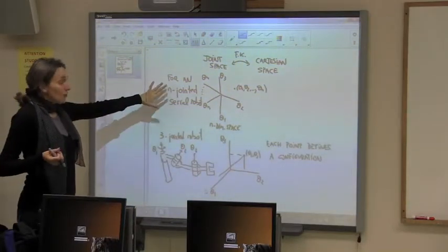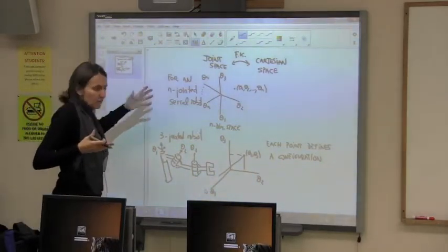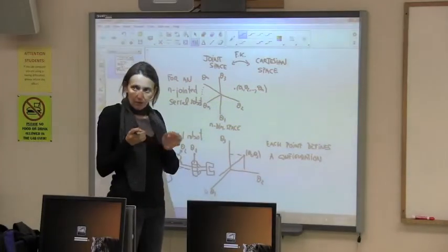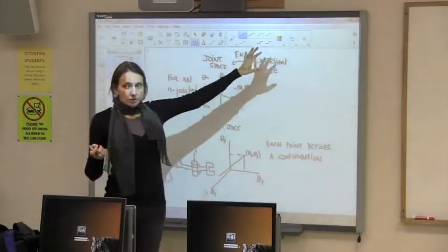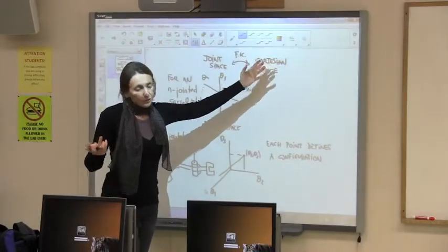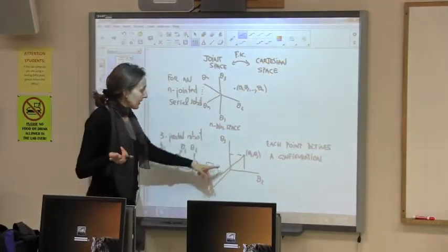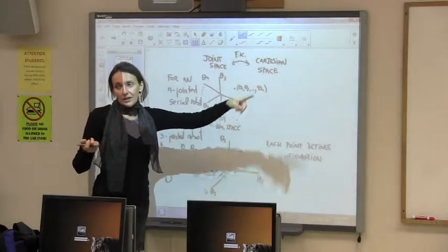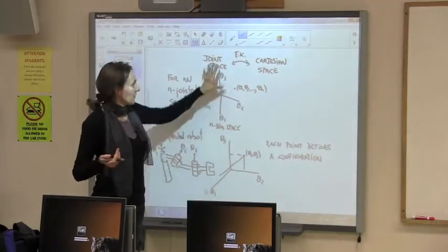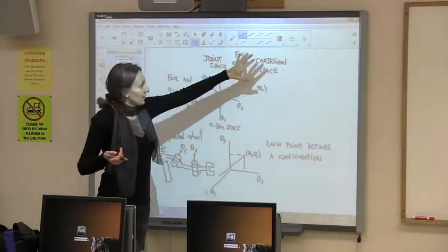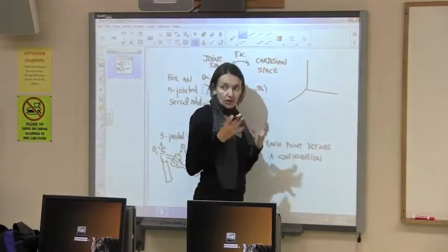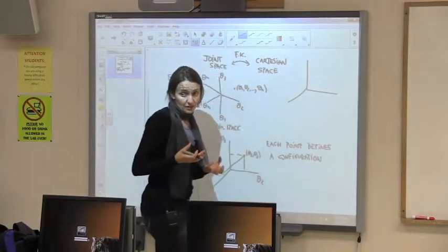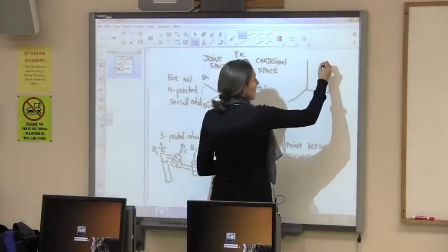So this is joint space. In some sense it's simpler because you just worry about a scalar for each dimension, but it's not so useful for us. Getting a straight line here doesn't mean you get a straight line in your Cartesian space. That's why we have this mapping here. On the other hand, the Cartesian space is our standard 3D space, but for rigid bodies. So it's really a 6D space. You have rotations and you have translations.